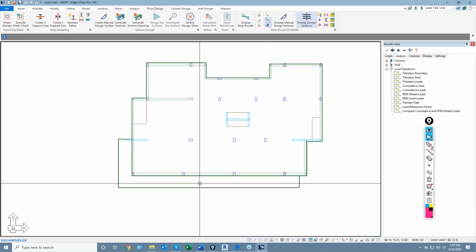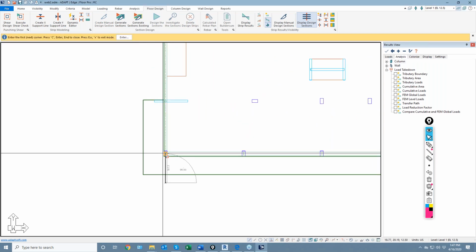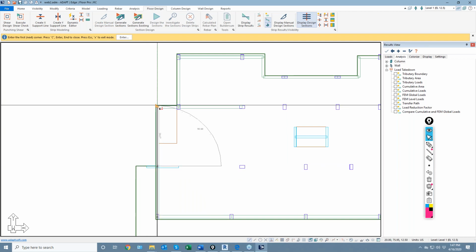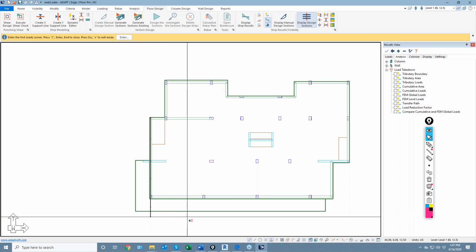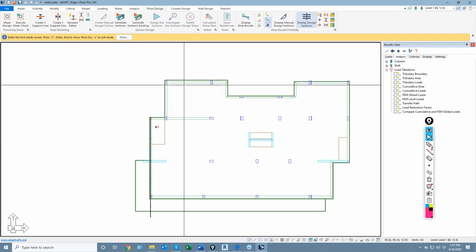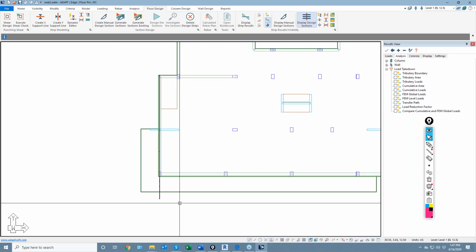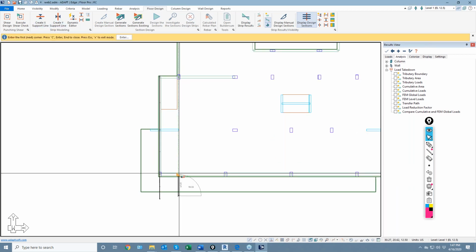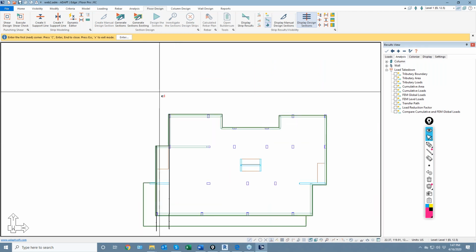I'm going to just isolate, and we'll do the Y direction now. So this direction is similar. We have really beams in both directions. I'll go over here. I'm going to say a middle strip might fall along this path, or it might fall here and kind of bend over. So I'll just go up to this point. Actually, no, let me come back over here. I'm going to go from this point down to this wall and just continue up this stream.